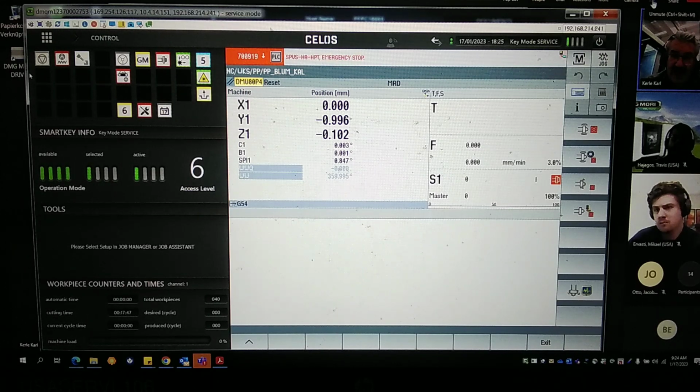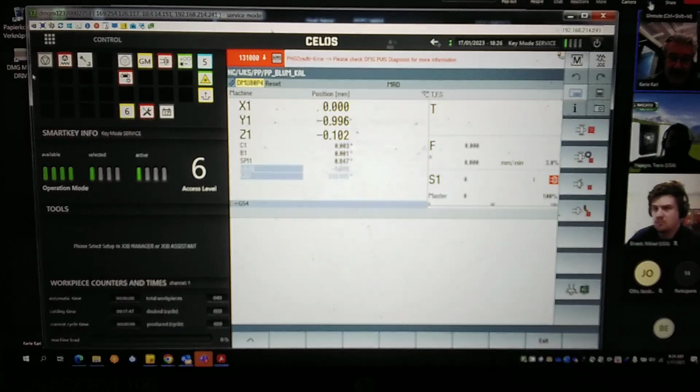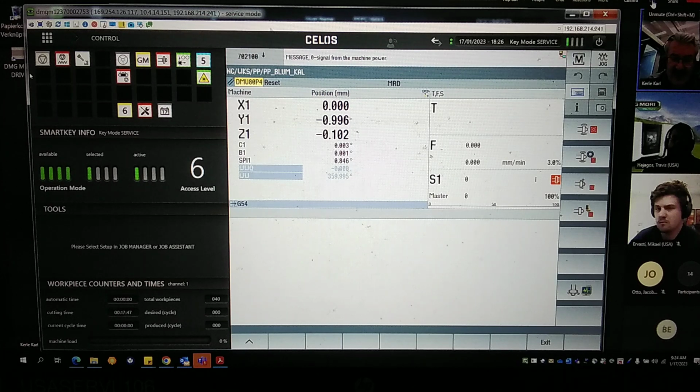And here we have a special teach mode, also to save these vibration values at several spindle speeds within the IFM box a second time, okay? That's like a reference value then, how good or how bad the spindle is after the machine arrives at the customer. Why?